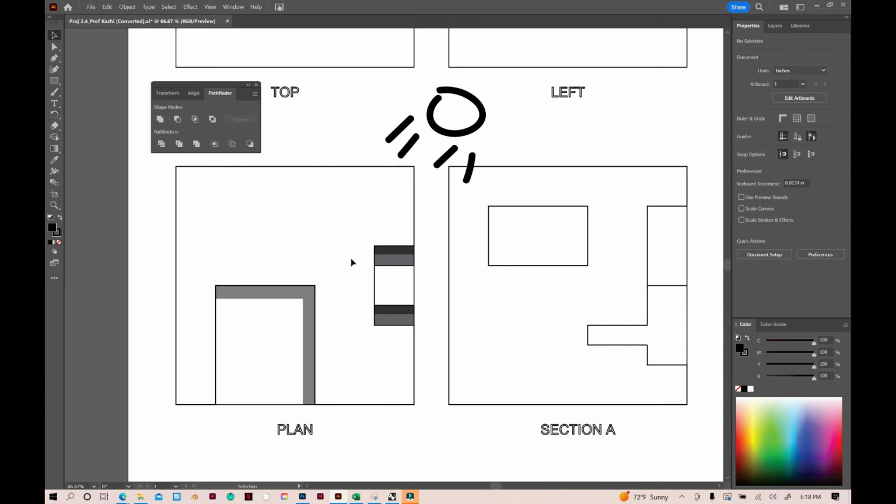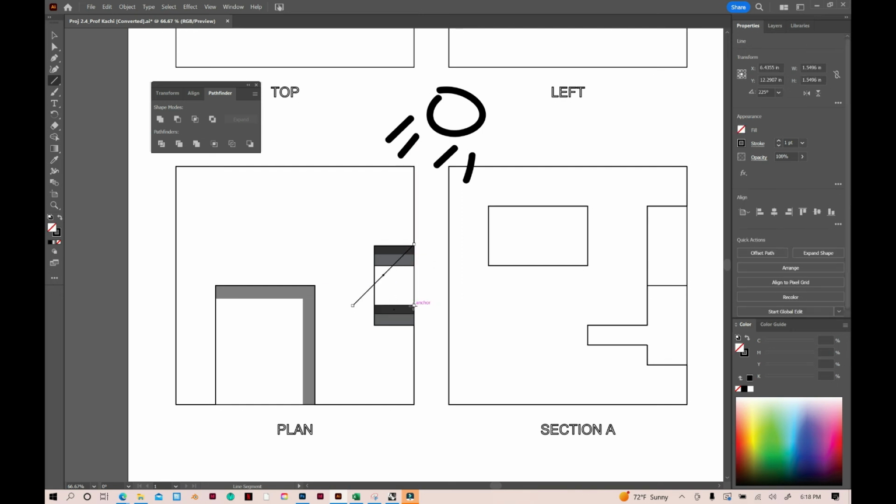So, before we continue, you're going to notice that this is slightly off. Since we don't have a wall here, the shadow casted would also be at that 90 degree because there's nothing stopping it here. The sun is going to keep penetrating through at that 45 degree. So we're going to do that same guideline. We're going to make our 45 degree angle, holding Shift. Do that for both parts.